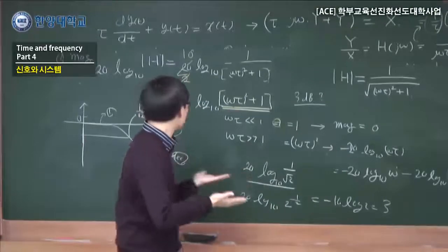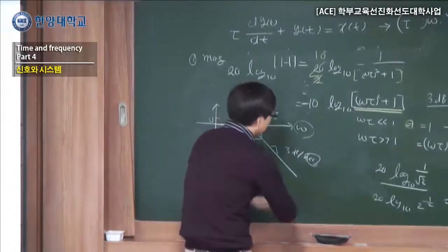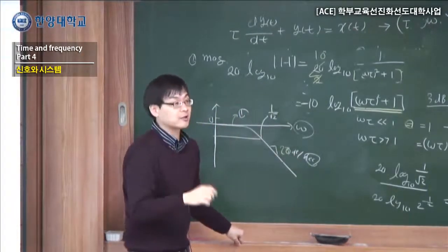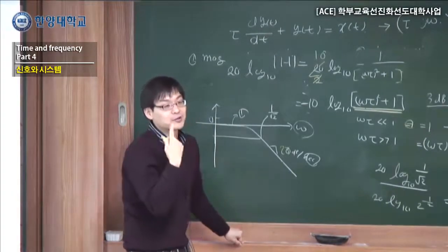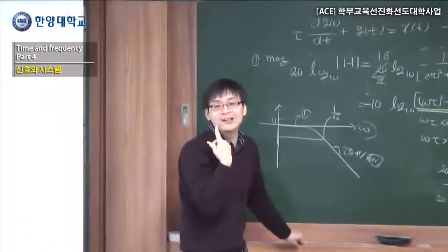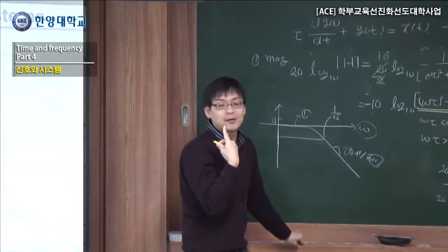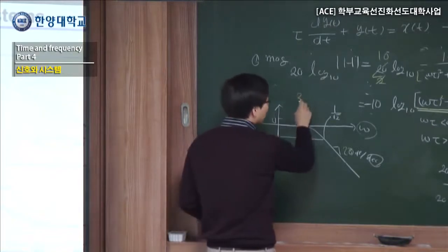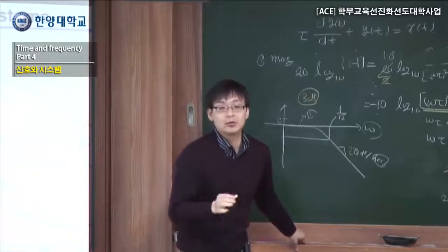So a 20 dB decrease per decade is correct. I intentionally put 3 to make you confused because 3 sounds very familiar, right? You have to hear about that in very many cases. Those 3 dB are used when you calculate your bandwidth.